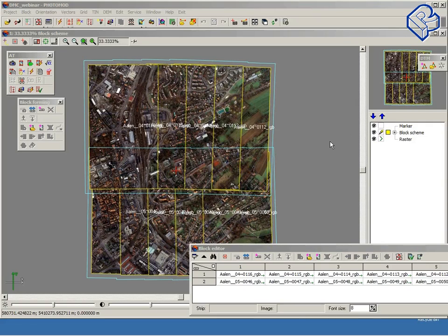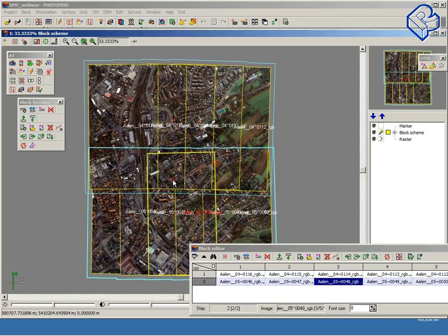Sasha has measured the accuracy of external orientation before starting tie point recognition. Probably you mean the accuracy of block layout. There is no way to estimate the exterior orientation accuracy before the solver, before having some checkpoints. But the idea was to estimate the accuracy of the block layout, because I will repeat it quickly.